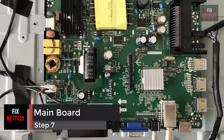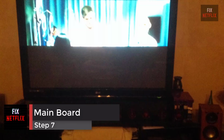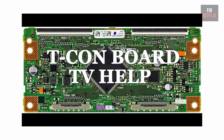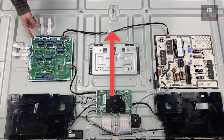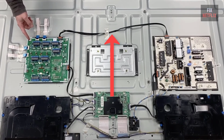Step 7. Main board. Now we check the main board to see if it is the culprit. If a problem shows up on half the screen or only a portion, it is likely the main board, rather than the T-con board. Make sure the TV is unplugged. Plug in the cable running between the power board and the main board, which was disconnected in the previous procedure.